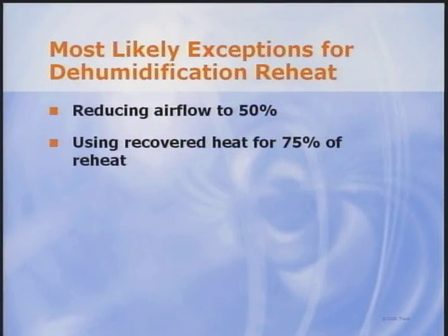However, if you decide to use supply air temperature reset and have humidistatic controls to ensure proper space humidity levels, you need to either reduce the airflow to 50% or recover the energy used for reheat. I was in Puerto Rico in September of this year discussing humidity control, and heat recovery has been used for years there to minimize energy use. At 25 to 30 cents per kilowatt hour for energy costs, there's a real incentive to recover heat.